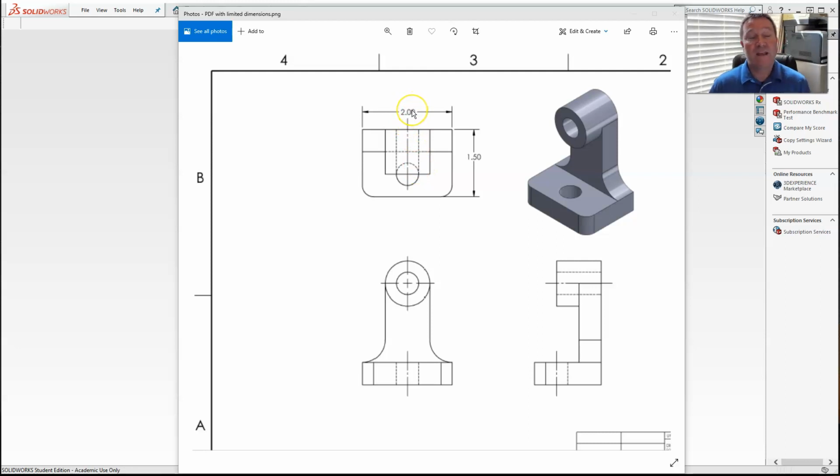here's an engineering note. When you are designing or trying to reverse engineer something and it looks symmetrical, you can assume that pretty much all the features in it are symmetrical also. If this were to have, let's say, holes on the sides, if you drew a line down the center, those holes would be exactly the same distance away from that center line.